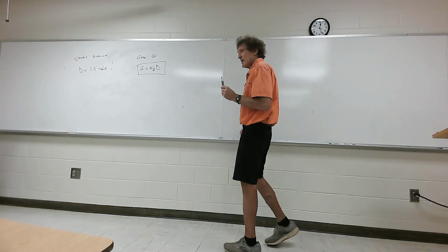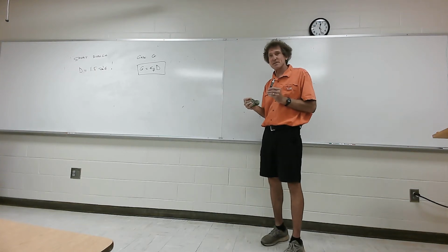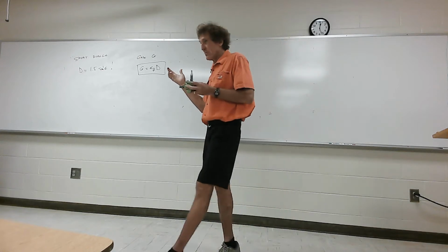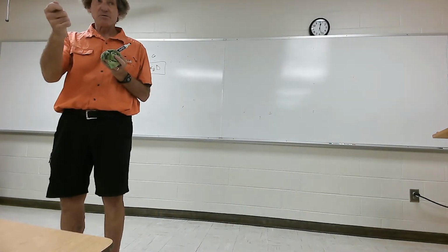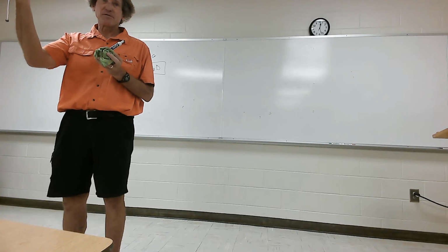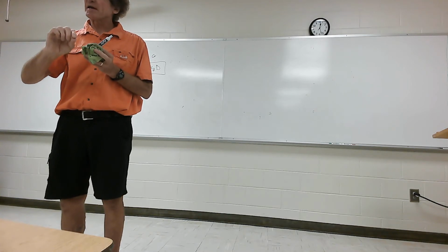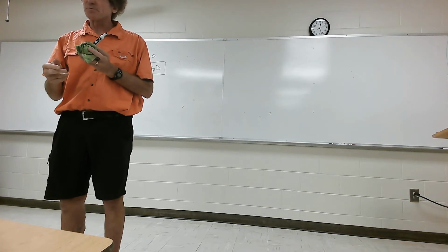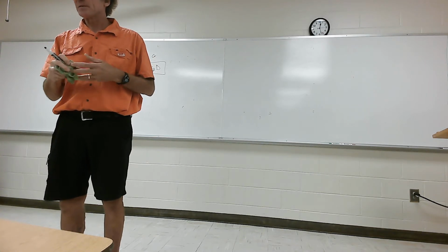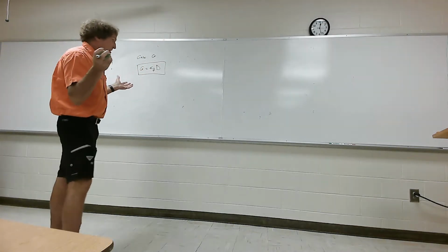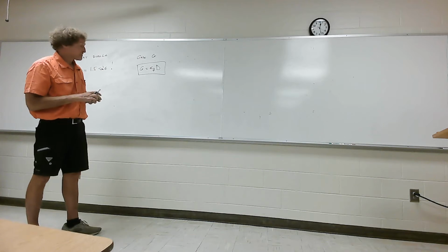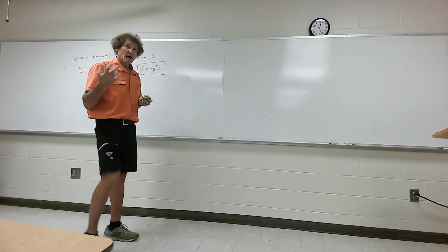Were you ever told to minimize the amount of solder? I'm just curious about this. How many have actually done any soldering here? It used to be everybody did. I think most of you had. We were always told they had these solder suckers. I don't know what they use. And you're not supposed to have any more than the lightest amount of solder, and you're supposed to have your leads as short as possible. Whoever built that antenna apparently missed that lecture, because that's as taboo as it gets, but it was done that way.